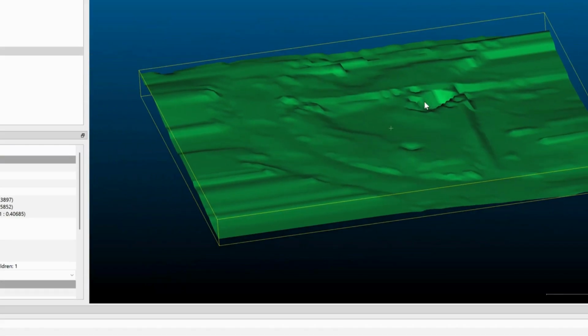But Revit could handle more than 10,000. Unless you have a really good computer, it struggles with more than that. Even if you throw 100,000 at it, it'll do its best to calculate those points. It just becomes too heavy at that point. Typically when we do topography at that scale, you don't want to make it that big. That's too many points. It's trying its best to generate topography, and 10,000 is the sweet spot. Anything bigger than that, just export an actual mesh.